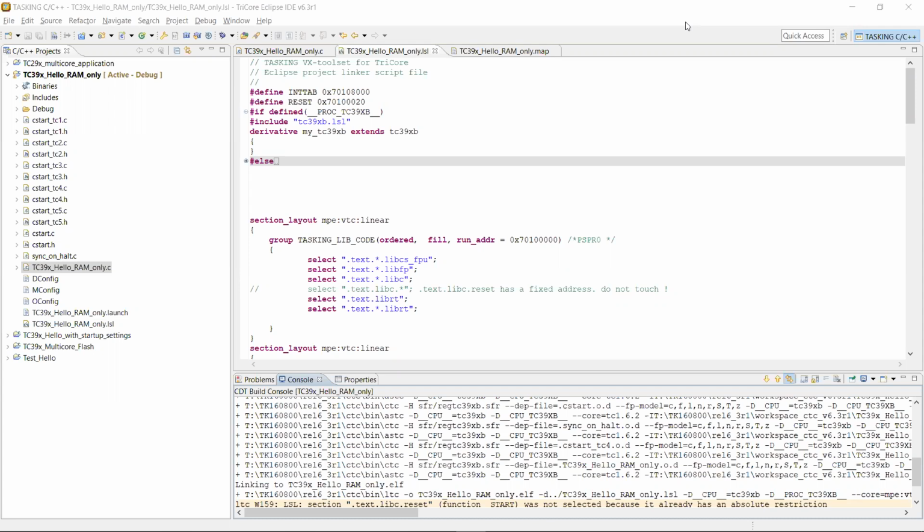There are certain limits on rewritability of the flash that are being documented with the TriCore. It's deep down in the documentation, and I don't really have the numbers in my head, but if you run your application often and you reflash and reflash and reflash, you will hit a number of programming cycles where sooner or later the flash will degrade, and the chip manufacturer like Infineon will only warrant a specific amount of reprogramming operations for the flash.